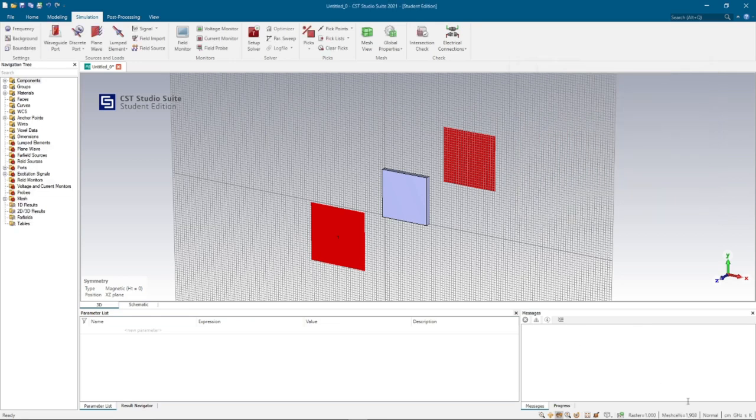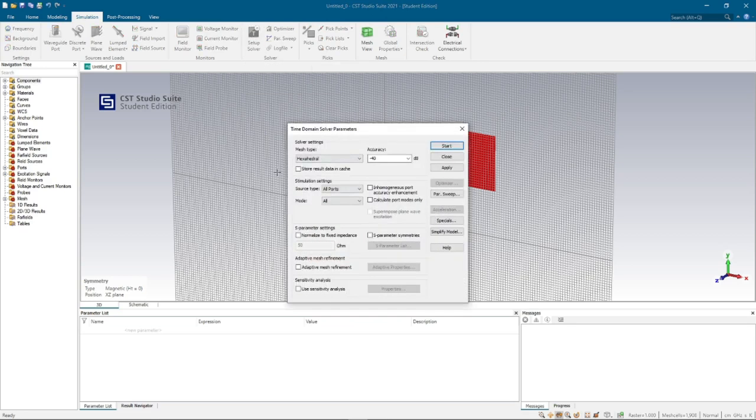Click apply and OK. As you can see, the mesh cell is now 1908. So this should be good for our simulation and then for the rest of the materials. After that, just run your simulation. For this one, you don't need to change anything, just click start.